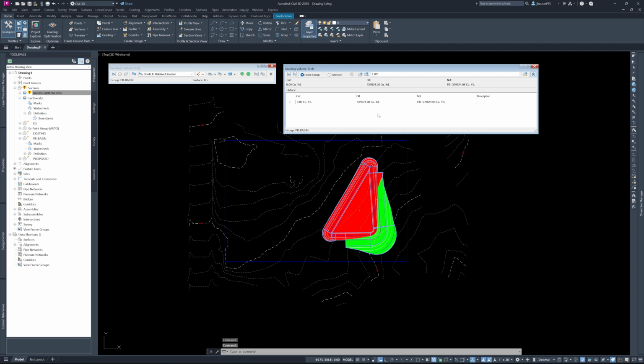But we can take this, and it has different options where, well, I think it's this one here. We can actually hit on this very far one over here. We want it to be a, let me see, a balanced cut earthworks. And you can see it moved things. It lowered the group from our original elevation to this elevation. And now it says that the cut fill should be really close. We're only 26 cubic yards off.